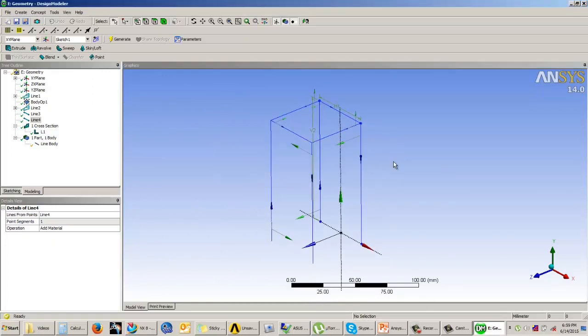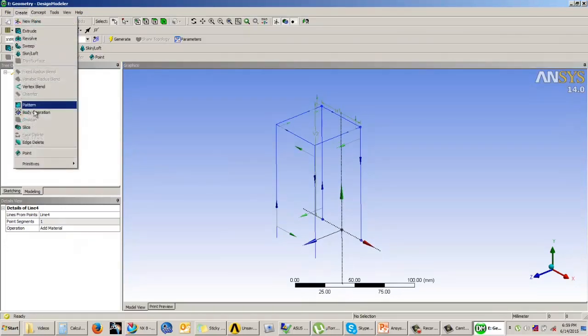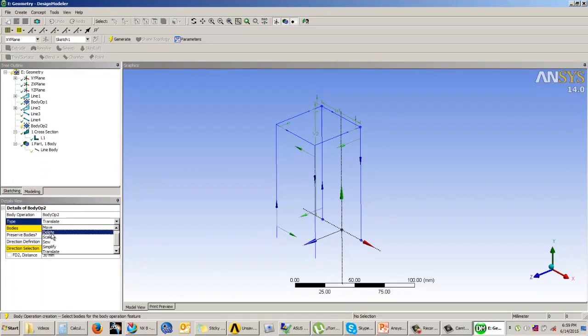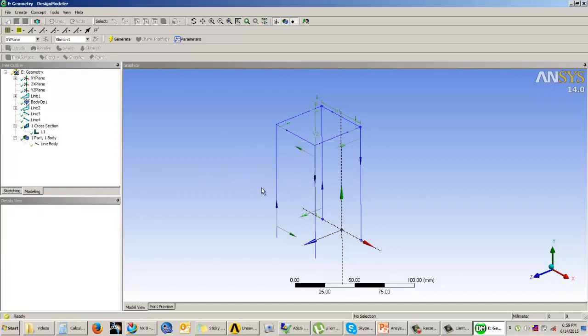With this, we have completed the modeling part in Ansys Workbench Design Modeler. Now we know how to create geometries, 3D models, how to create 2D models, how to create 1D models, how to create assemblies, how to add features. There are some more options over here. That is, in body operations you can use move, delete. Okay, if you want to delete anything, if you want to delete a body, you can use the delete option from here. You can also create a mirror option by using the body operations. But these body operations will only work on bodies and it will not work on sketches.